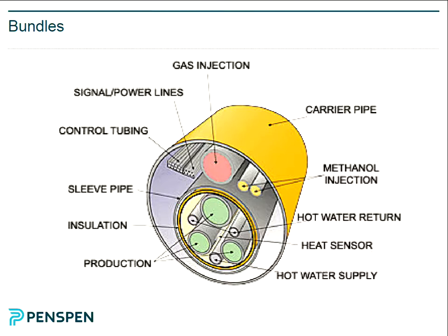From a process point of view, the topic today, it allows you to add lots of insulation. It also allows you to heat this pipeline bundle with hot water. You can run hot water inside the bundle, heat it up on the platform, run it down inside the bundle, and then return it and recirculate it. There's at least one field in the North Sea which works like this.